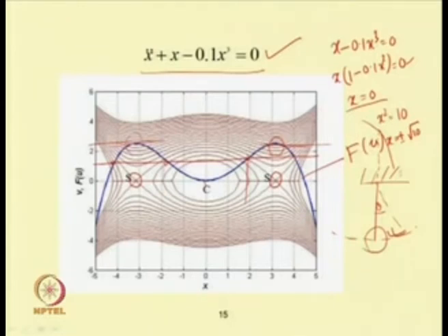Corresponding to these 2 maximum points we have saddle points. In between these 2 saddle points the response of the systems is periodic, and outside the saddle points we have 2 solutions. So in this case, near the center we have periodic response of the system.